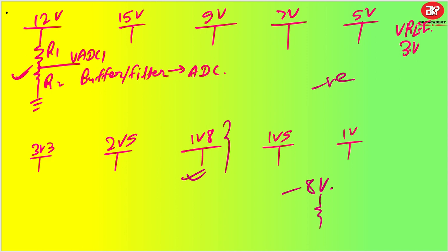In that case also you can go ahead with your voltage division, and then use a bipolar IC which will take negative values as the input also. At the same time, if you want to utilize your microcontroller ADCs as the monitoring device for this particular voltage level, what will you do? You can send it to an inverting amplifier, and then you send it to your ADC.